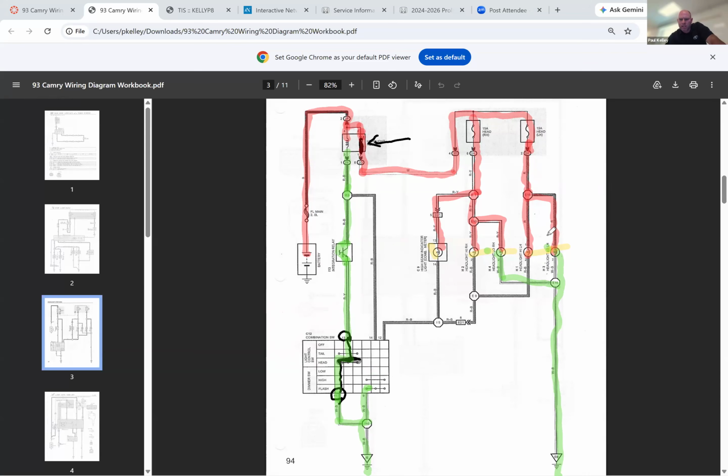What if the customer stated they had a problem with the high beams? We would probably have to turn on the high beams, would you say? So if you wanted to turn on the high beams, how do we do that? We would go like this, high beam. That connects 9 to, not to 11, not to 14, but to 12. Cool? And if 9 is connected to 12, now let's see what happens.